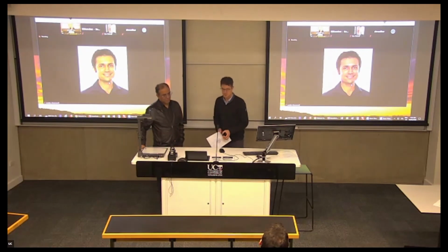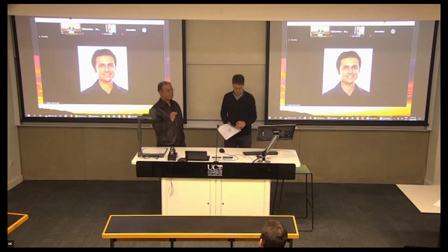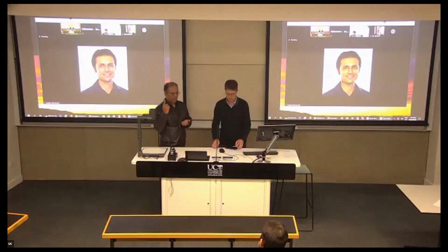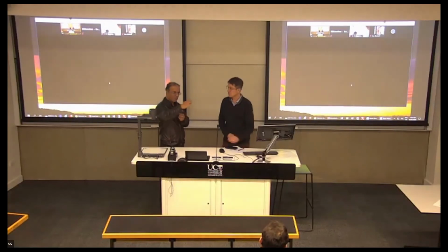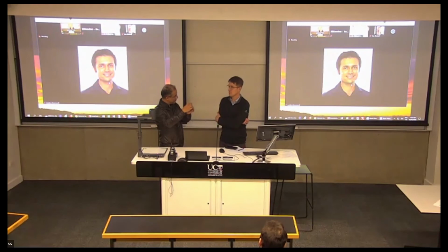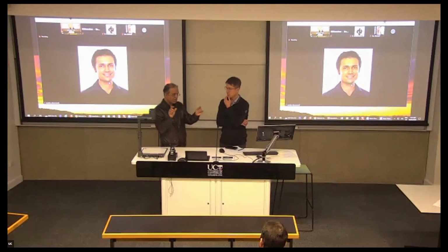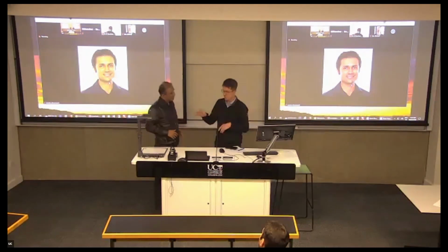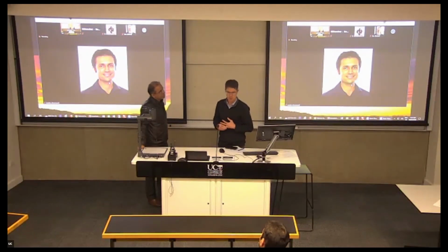Yeah, for the diaphragm, I believe the problem lies in the way that we construct rather than the way that we model. If we identify a way to not continuously connect it throughout the perimeter, then we can avoid the plastic hinge part at the end of the beam, and not require the floor to follow that deformation. Because the elongation is concentrated only in the plastic hinge, not in the middle part, and you can transfer the shear through the middle part. So you would constrain just the middle nodes in your diaphragm.